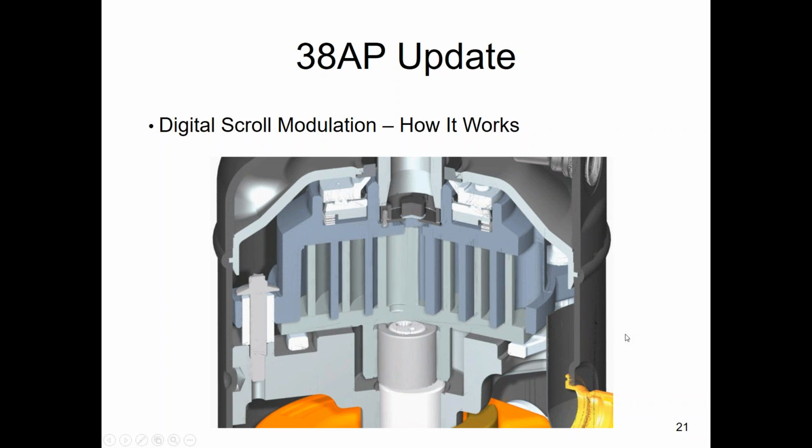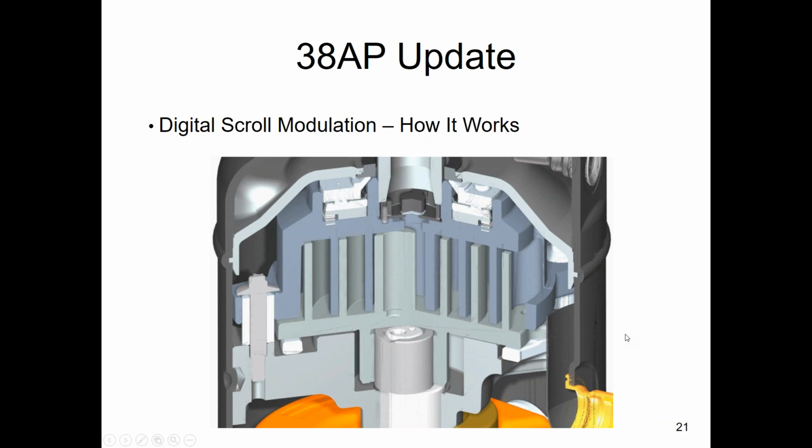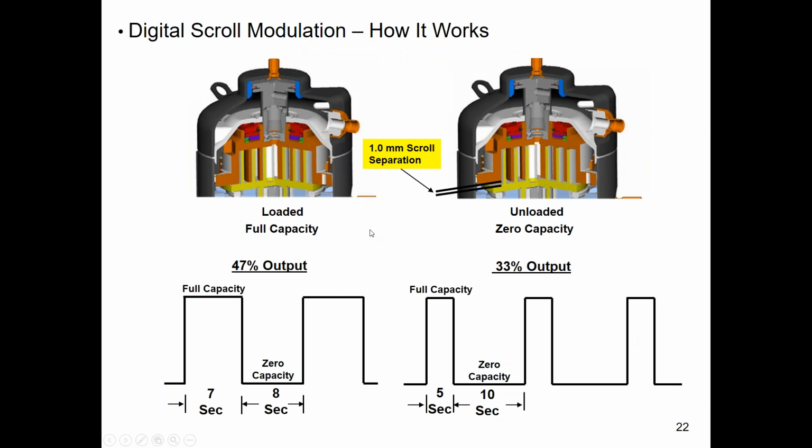So when we look at the unit and the available tonnage for minimum oil entrainment, we look at what this compressor does at 100%. So it's either pumping or it's not. So you look at the compressor tonnage, not necessarily the percent of capacity of the entire condensing unit. Let's say we have a 38A PD, which is a dual circuit Carrier condensing unit. That's a 38A PD 100.